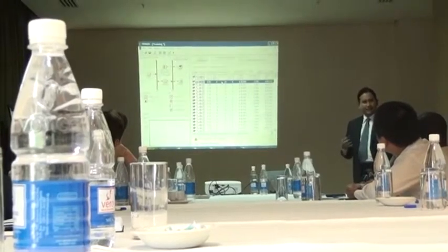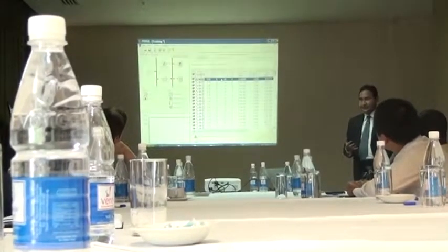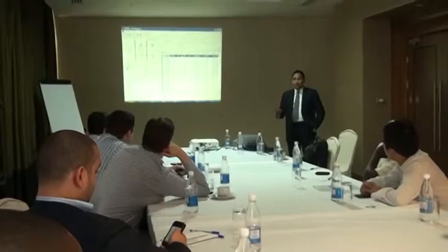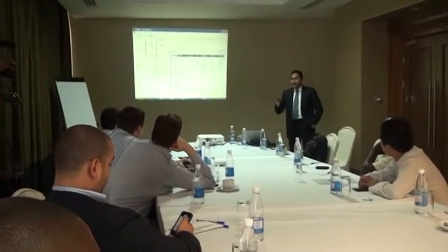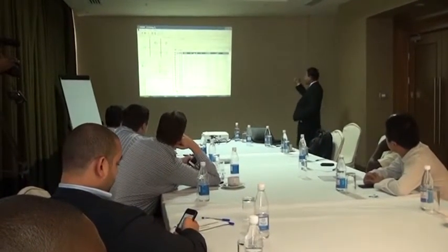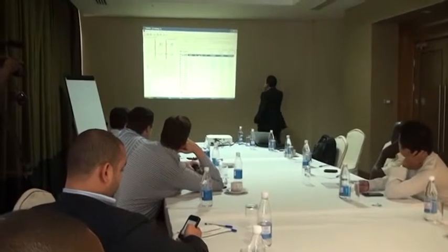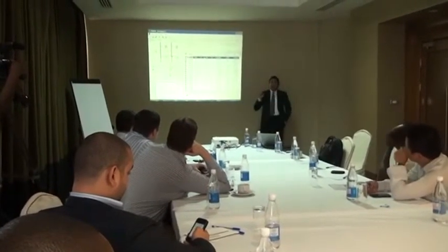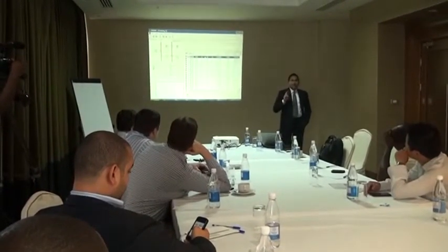Many operators have a strategy of using the diesel genset for about 3 hours average per day, which is about 100 run hours per month, and then you come up with a different approach. The fourth element is the overall operational cost, which one is showing lower. So these are the 4 areas to look at while selecting the sites or solutions from here.